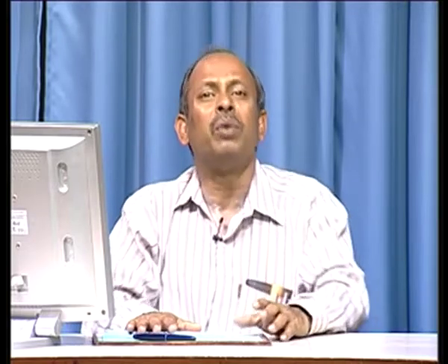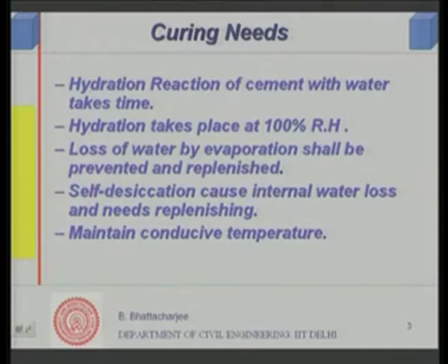So, this water has to be replenished or supplied from outside, and its evaporation loss should be restricted. This process by which we prevent loss of water through evaporation or drying of concrete, and also supply additional water to replenish the loss of water, that process we call curing, and it takes place over a period of time. So, we have seen the needs of curing and also how we do it.